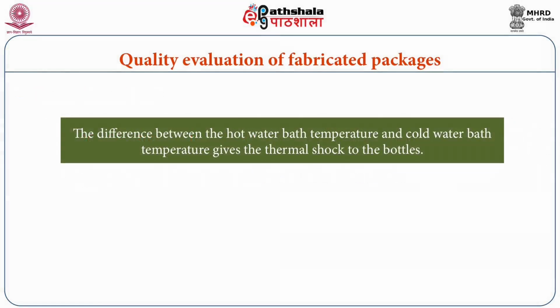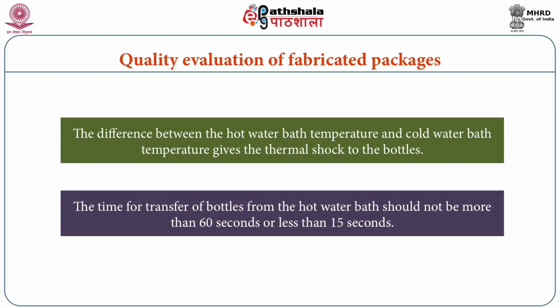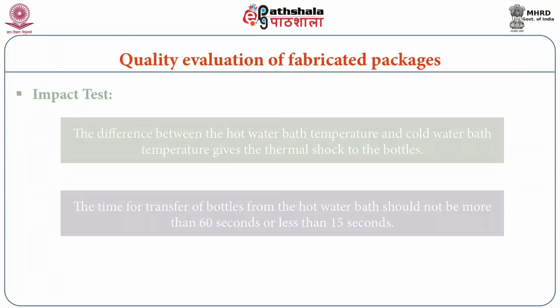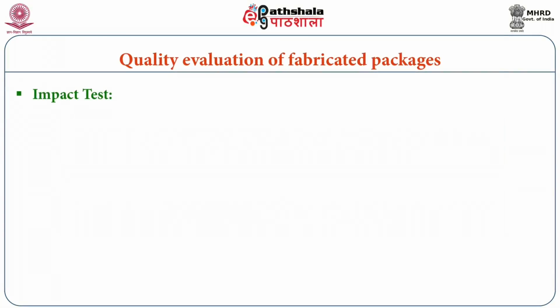The difference between the hot water bath temperature and cold water bath temperature gives the thermal shock to the bottles. The time for transfer of bottles from the hot water bath should not be more than 60 seconds or less than 15 seconds. The next test is impact test.